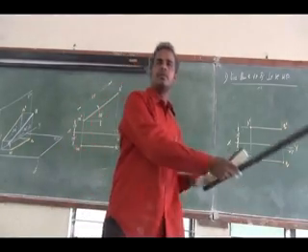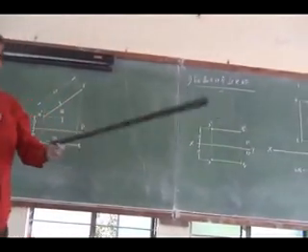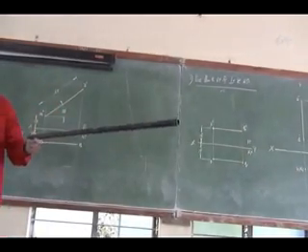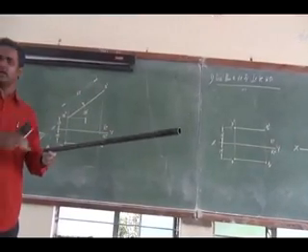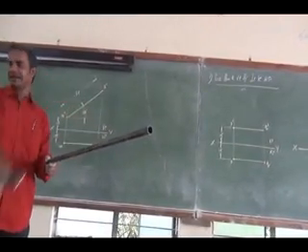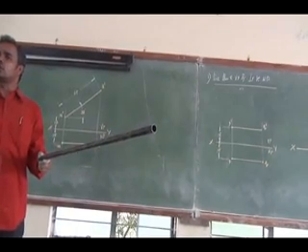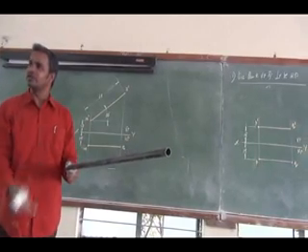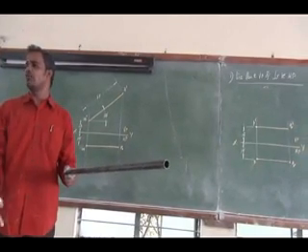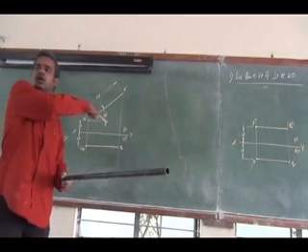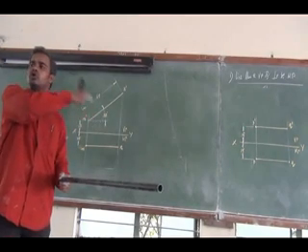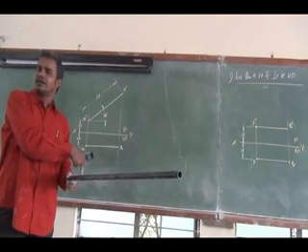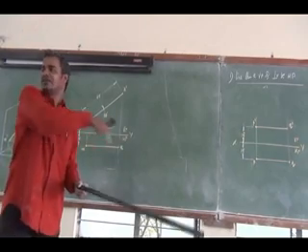In this case, you see here, the line is like this. One end is given, it is 15 and 15, and it is 30 degree inclined. So where will I obtain the true length and true inclination? I will obtain them on the horizontal plane, that is nothing but my top view. I will obtain a straight line on my front view, which will be the apparent length, parallel to the reference line.